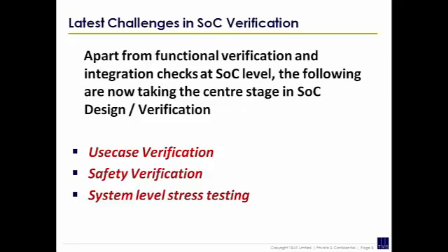What is the problem with use case verification? The simulation runs for at least 2 weeks or something like that. You start something, the scenarios or something like that, it takes the license and keeps running and running and running. So most of the companies are now thinking of prototyping and also thinking about emulation for use case verification.